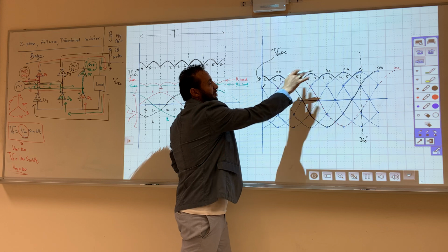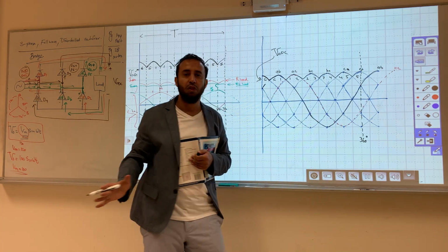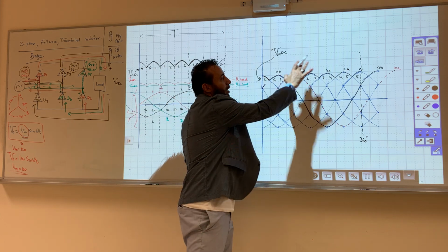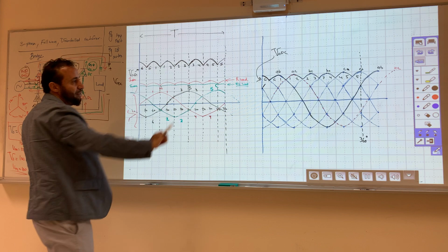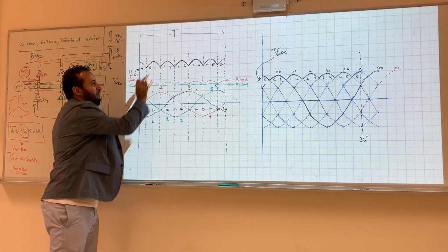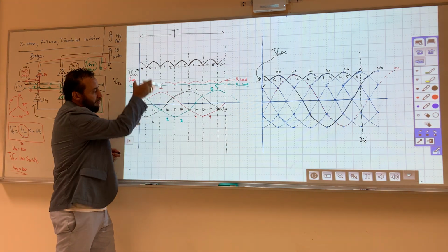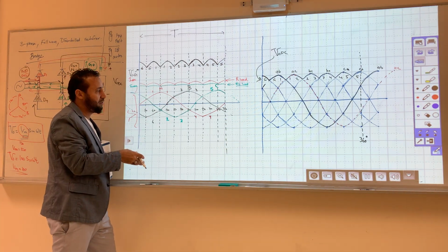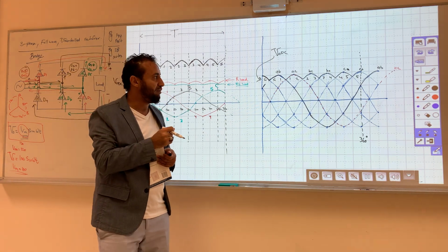You will not see all this on the oscilloscope. All you will see is the highest points, which is the V out DC. So you can draw the V out DC using the V source and make a line through the peaks, or you can draw the bridge and then find V out DC.